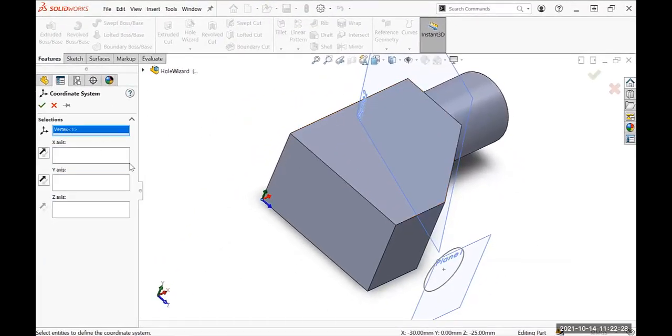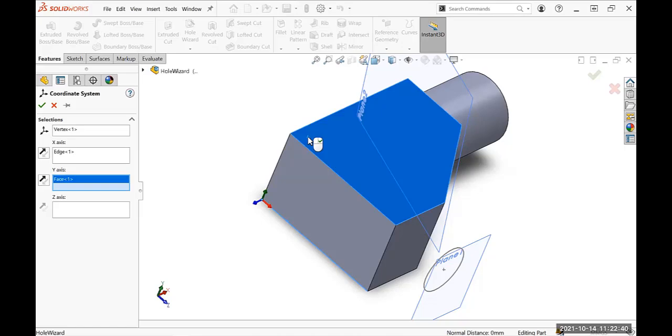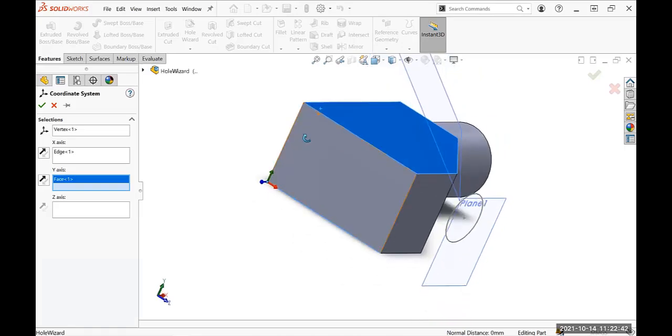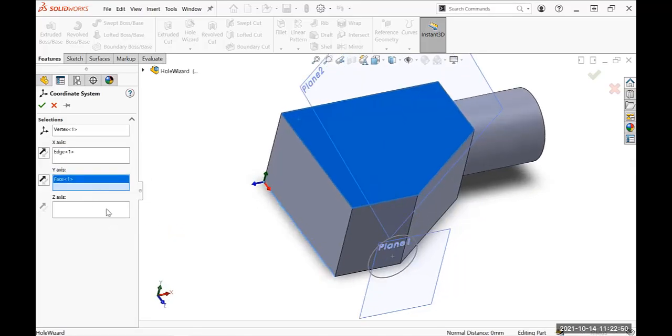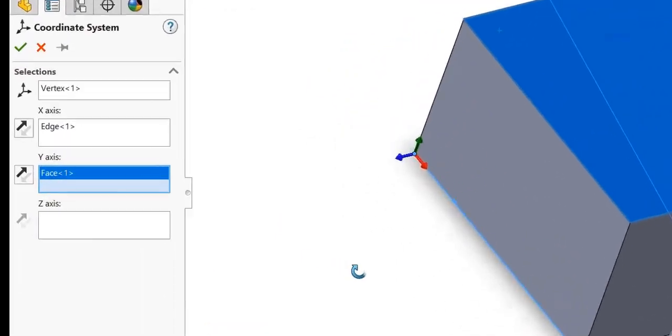And you select the origin point. I have the vertex there, and select this axis here. That's an x-axis. And then you have y-axis. You can either choose a line or any plane that is normal direction on that one. And you don't have to select all three, because if you make it two, the third will be automatically determined. So if you select another one, that'll be redundant.